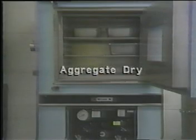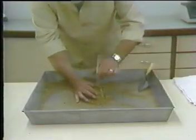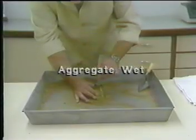Bulk-specific gravity based on the oven-dry weight of the aggregate is used when the aggregate is dry or assumed to be dry. Bulk-specific gravity saturated surface dry is used if the aggregate is wet, that is, if water fills the pores of the aggregate.